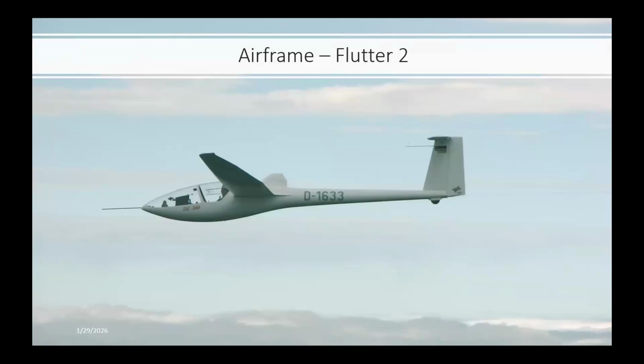So the conditions of this flight were specifically set up to test if the aircraft would respond as the computer models predicted. And by the way, it did. This is a DG300 modified to 17-meter span. The additional span was not added at the tips. It was added by putting in plugs at the wing root. So they beefed it up.